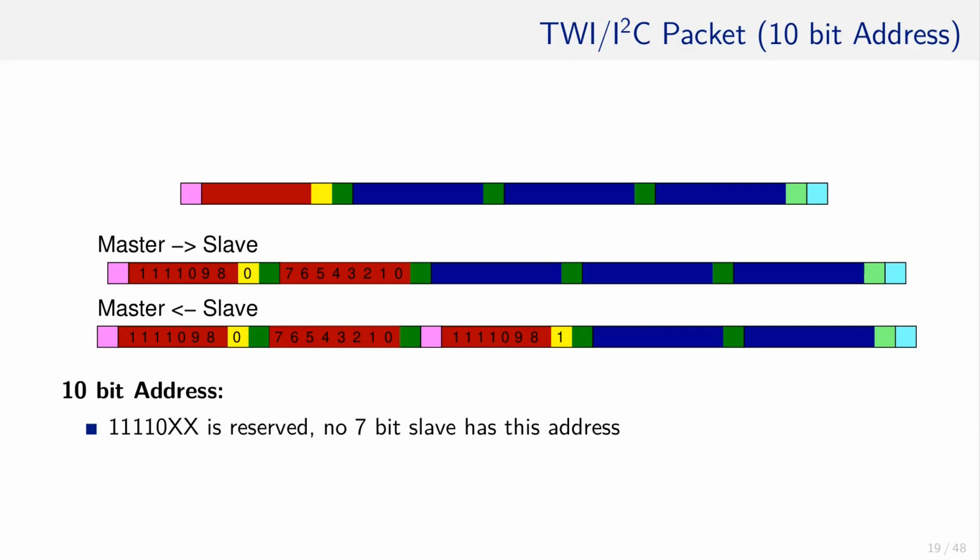After the acknowledgement, the master writes the second byte, or in other words, the remaining 8 bits of the 10-bit address, which is again acknowledged by the addressed slave. However, the slave is in a "I have to receive data from the master" mode by now. To change the mode without letting go of the bus, which then could be reserved by another master, the very same master sends again a start condition without terminating the transfer. That second start condition is called a repeated start.